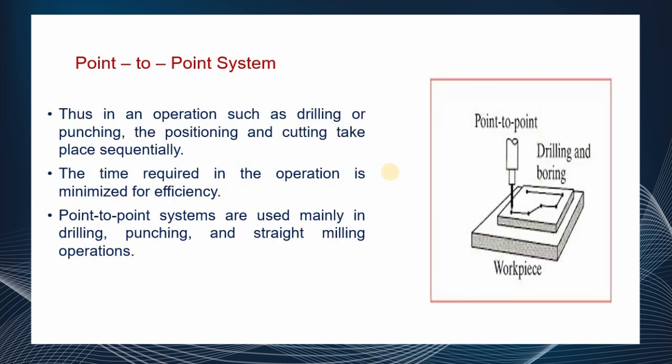Operations such as drilling, punching, positioning and cutting take place sequentially. All these operations take place sequentially as prescribed in the set of instructions. The time required in the operation is minimized for efficiency. The point-to-point systems are used mainly in drilling, punching and straight line milling operations.